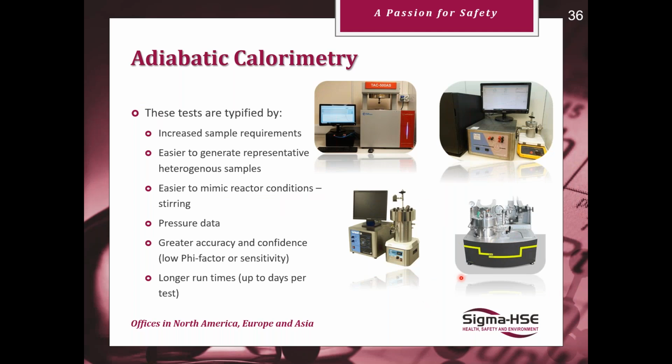So these last three tests I mentioned are quite adaptable. It's possible to perform additions under agitation, impose back pressures, and we can accurately simulate normal or worst case process scenarios. So these are the sort of tests that are required for when you're trying to determine vent sizes for emergency relief systems.